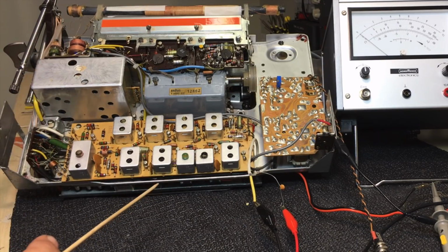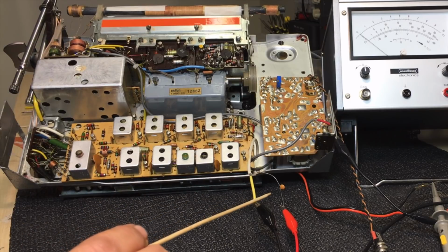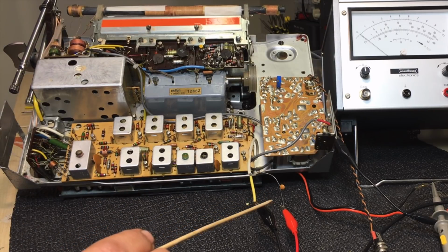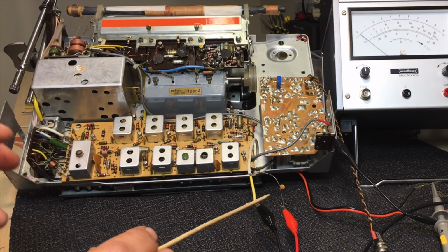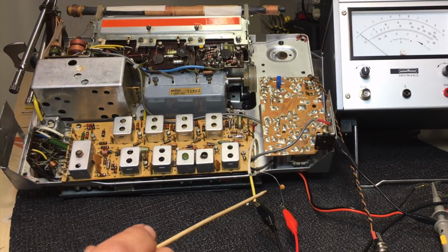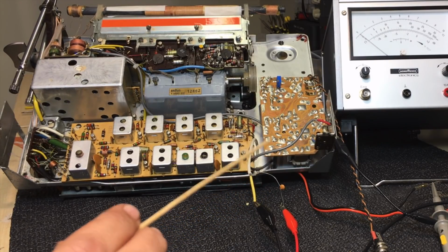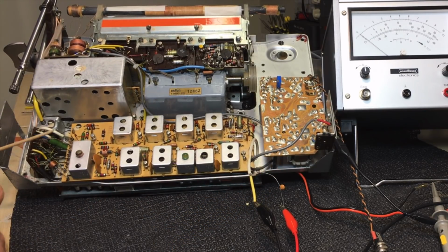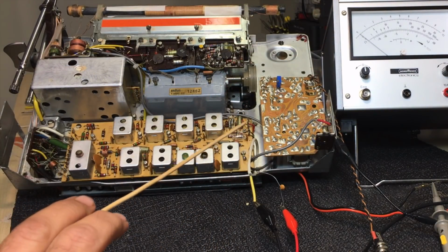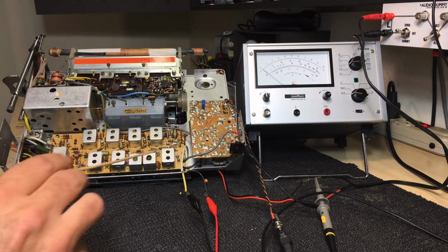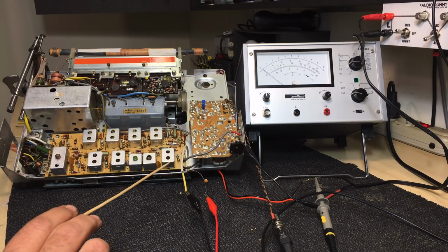So if everything is well aligned and you put in a 455 kilohertz carrier with a 600 hertz or 1000 hertz, in other words an audible tone modulated on there, you should hear the beep or the tone on your speakers. That's fine. However, when I couple the scope to this point it is so small that it's very difficult to get a decent reading on the scope. And they're actually describing this as a wobulator setup.